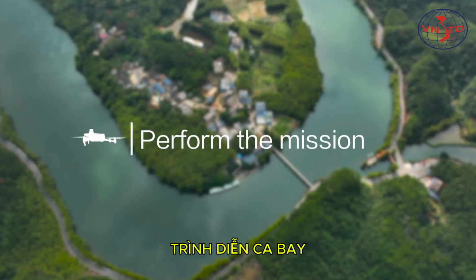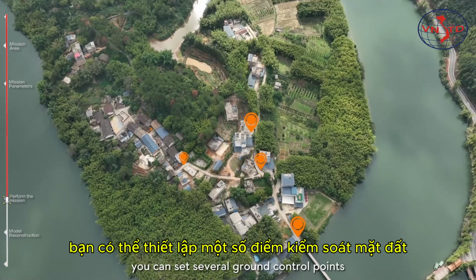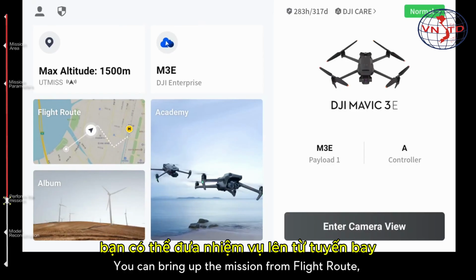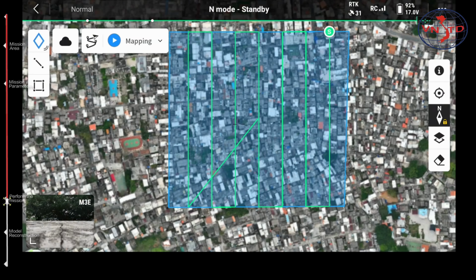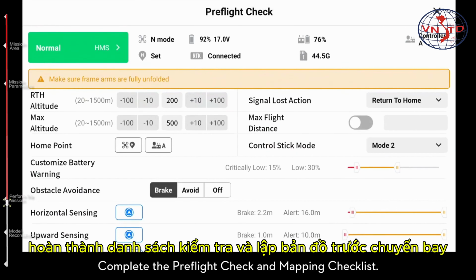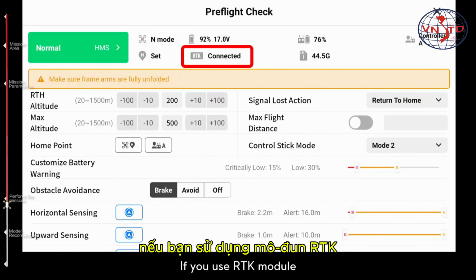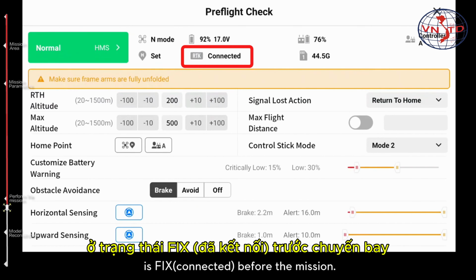Perform the mission. Choose a wide open area to take off. You can set several ground control points for data accuracy. You can bring up the mission from flight route, or use this icon from the flight view. Complete the pre-flight check and mapping checklist. If you use RTK module, make sure the RTK status is fixed before the mission.